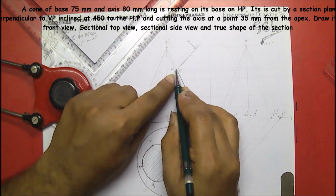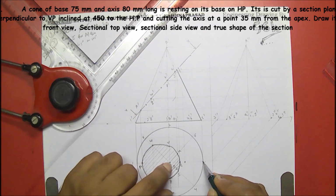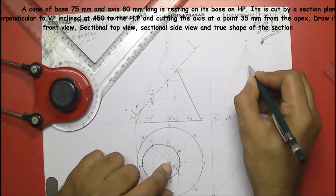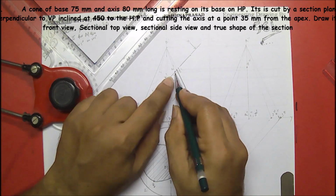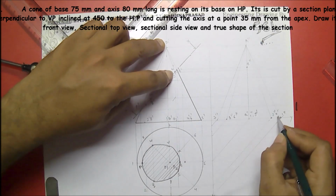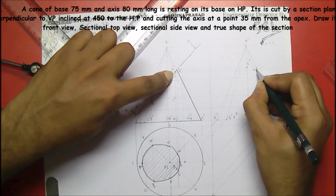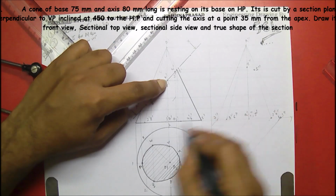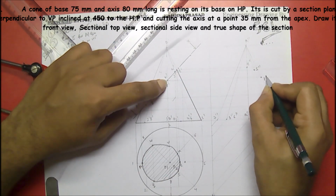Now project these points above here, right? T, that would be falling on 5 and O1. So this is 5 and this is O1, means T double dash. Next, U would be falling on 4 and O1. This is 4 and this is O1. U double dash. Next, coming to R, that is falling on 7 and 3. This would be the R double dash.